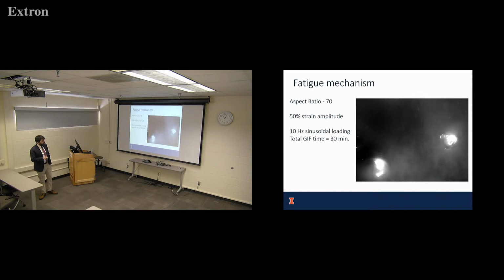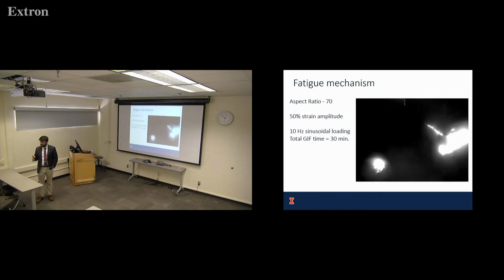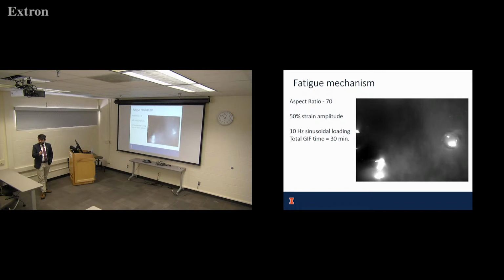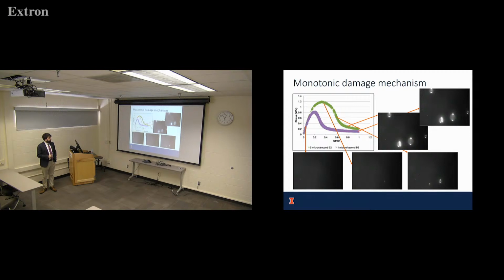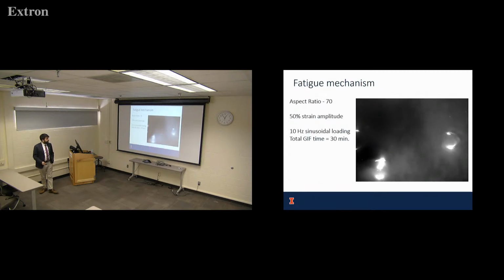Now the caveat here: usually with fatigue experiments, you need some kind of notch or some kind of initial seed for damage. In this case, we did have to apply some load and get it up to the peak so that a small cavity would form to see any damage. Otherwise, there was nothing visible, which was very interesting. Of course, there's a very high loading rate too, which again corresponds with quite a high strength here. So something to think about.